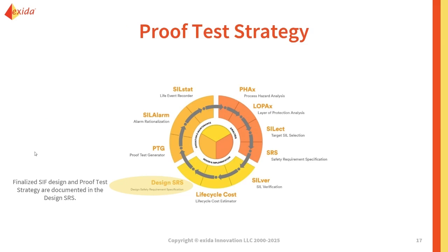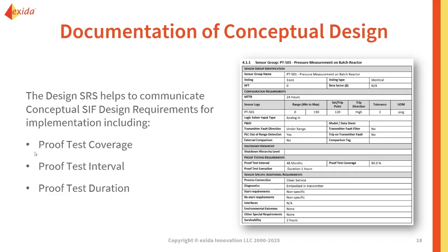Finally, once your SIF design is completed, you're able to communicate requirements for implementation using the design SRS. So much like the SRS in the analysis phase, now that we've finalized the SIF architecture, what devices we're implementing for our safety instrumented function, and what our maintenance strategy and proof test strategy is, we want to document that in a nice templated specification so that the people implementing the SIFs on site or carrying out the maintenance tasks have an easy way to access the requirements.